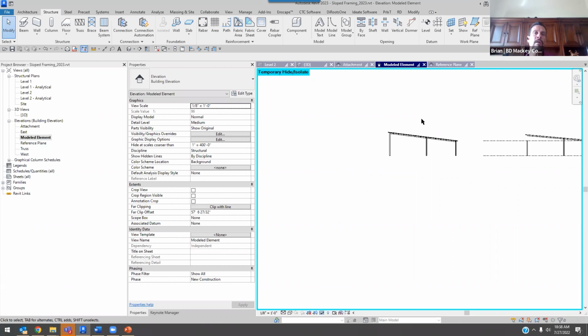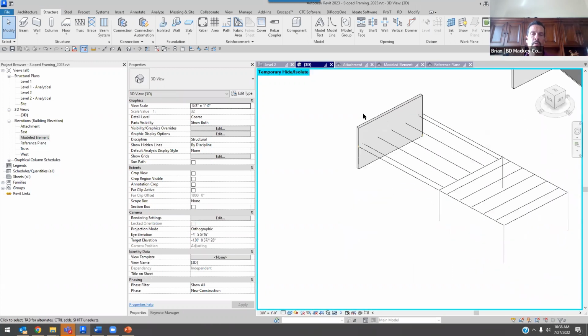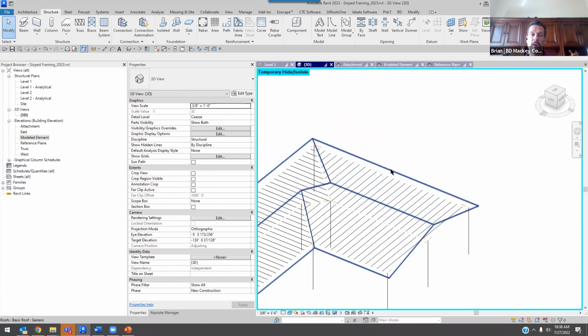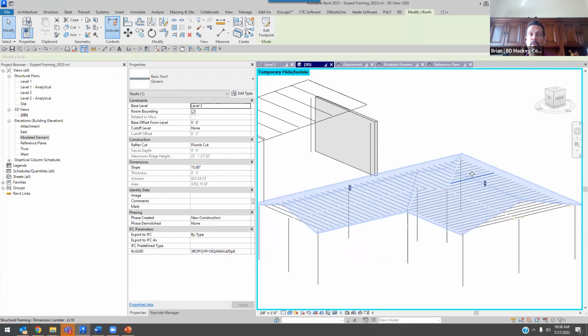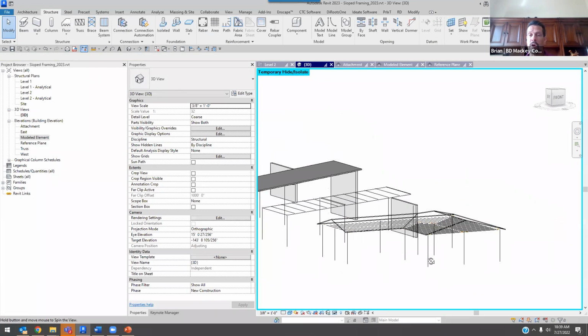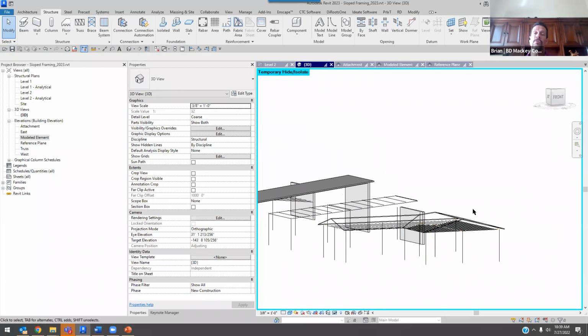A little bit of a pain, but if you're talking something like I'm going to show over here, yeah, this is my architect's roof. I copied it from the clipboard, paste same place, right? So when you do copy, paste same place, you'll get it right where it was. And then I'm going to take all of these columns and attach them. So if they update the roof, if they change the slope, whatever, copy, paste, reattach all the columns, I'm good to go.